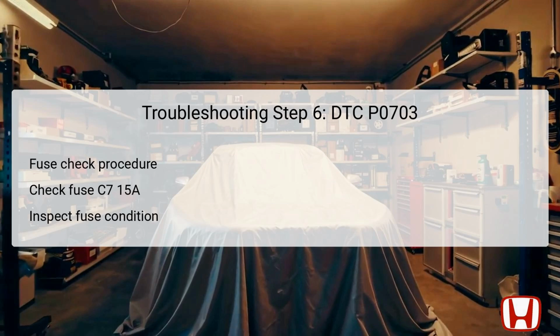If a replacement fuse doesn't solve the problem, inspect for any shorts in the connected circuits, as they could be the root cause affecting the brake pedal position switch's operation. Proper fuse functioning is essential for the reliability of electronic components in the vehicle. At Step 7, you will conduct a subsequent examination of the brake pedal position switch signal.